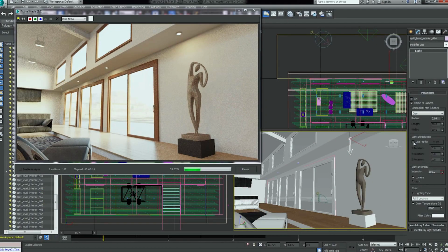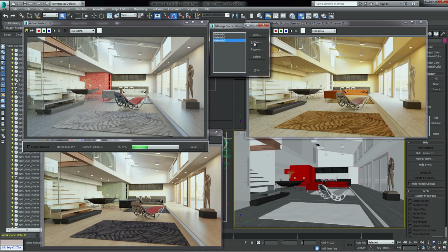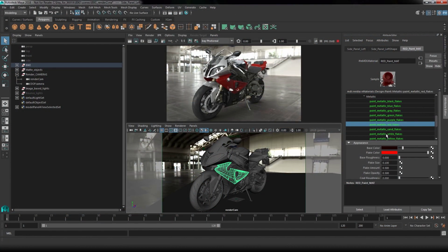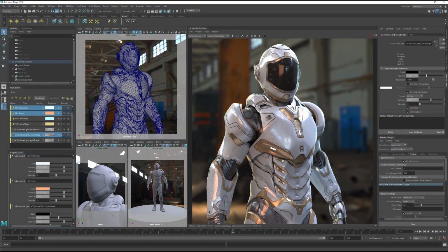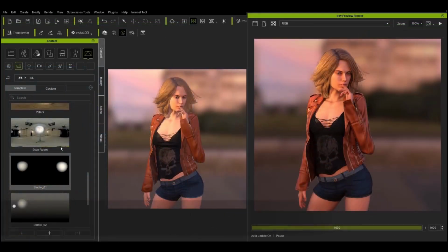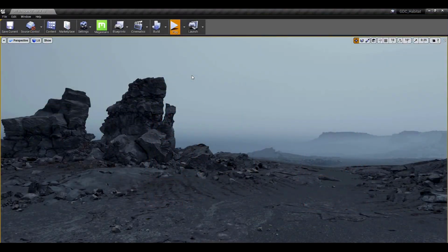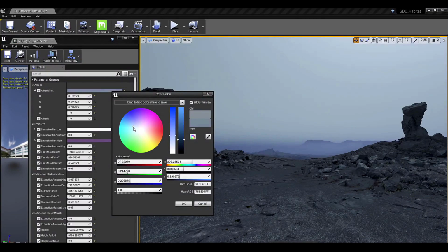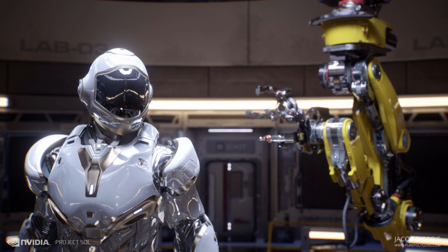Unlike conventional shading languages, which must individually define materials for each separate rendering engine, MDL materials only specify a set of high-level attributes, where individual renderers are free to implement more or less of the available MDL functionality, depending on their capabilities. Even a simple OpenGL-based renderer can still produce consistent, accurate results within its limitations, providing very similar physical accuracy in simulation to renderers that support the full range of MDL functionality, such as Iray.